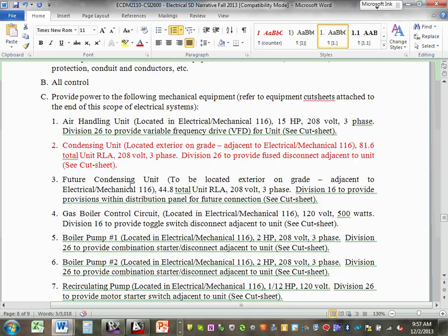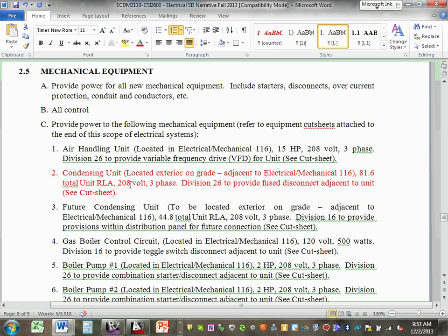Any comments, guys, about filling this information for the so-called mechanical schedule? It's time consuming, so we're going to fill it this time for this project, and we will be filling it for the next project, so you get used to the same schedule. If we are smart enough in Revit, this should be generated directly from Revit if you fill all the information and assign the conduits and so on. For the time being, you're going to use the schedule from CAD and import it in Revit. Okay, so that's basically the mechanical schedule.